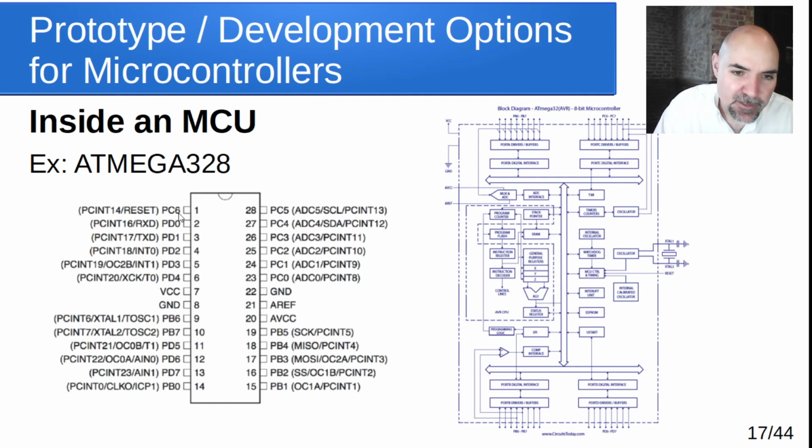But you'll notice if you look at these, this is port D0 through 4. Here's port B0. Here's D6 and 7. Here's port B6 and 7. If you look, these are all labeled PC, PD, PB. So these are all the different ports that are the I/O pins of that. And then other than that, you'll notice we have VCC and ground, that's power and ground. And here's AVCC, that's the analog kind of voltage supply.